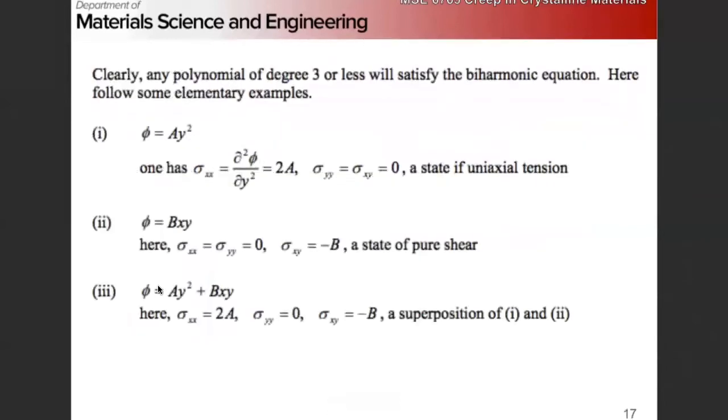So, depending on what boundary conditions we put in, we can do some really elementary examples. If we make our Airy stress function quadratic with no constant term in y, that turns out to be a uniaxial tension in x, right?